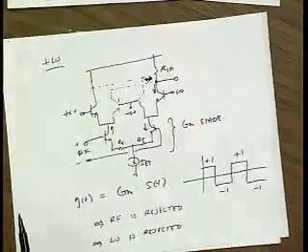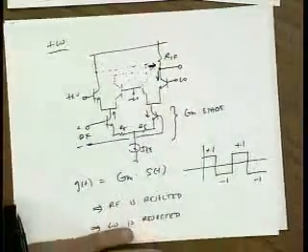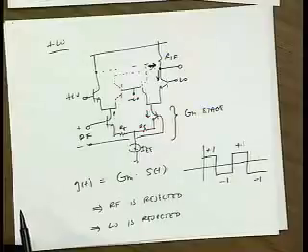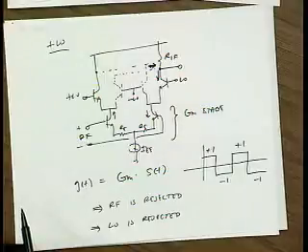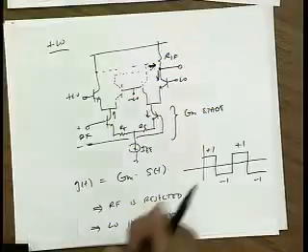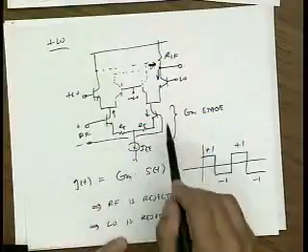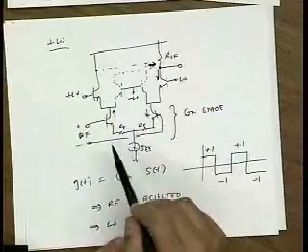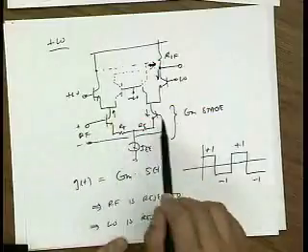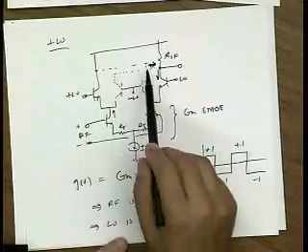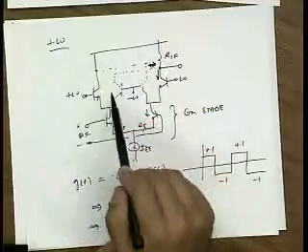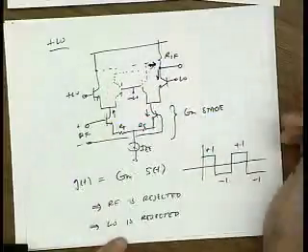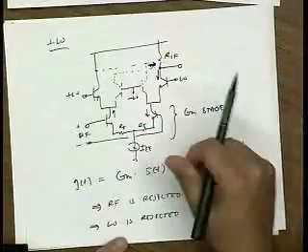Yes, Debo. So in the single balanced mixer, we saw that when we took the output differentially, the gain was doubled because of the square wave. Here again, if we now take it differentially, will it again be doubled? Yeah. Well, it's not +2 -2, because the input is degenerated. It's a differential pair, so we get half the gain down here, and then to recover the gain we take the differential output. So, comparing apples to apples, the gains are the same.